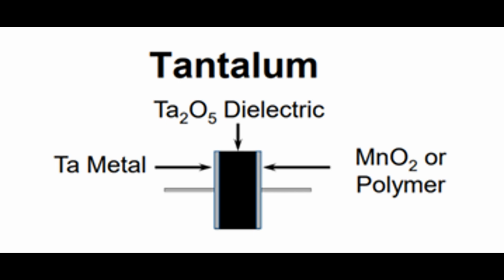9. Filtering. Decoupling capacitors. Tantalum capacitors are often placed across power supply lines near integrated circuits, ICs, to remove noise and stabilize the voltage. This process is called decoupling. They help smooth out power variations and suppress noise from other components in the circuit.